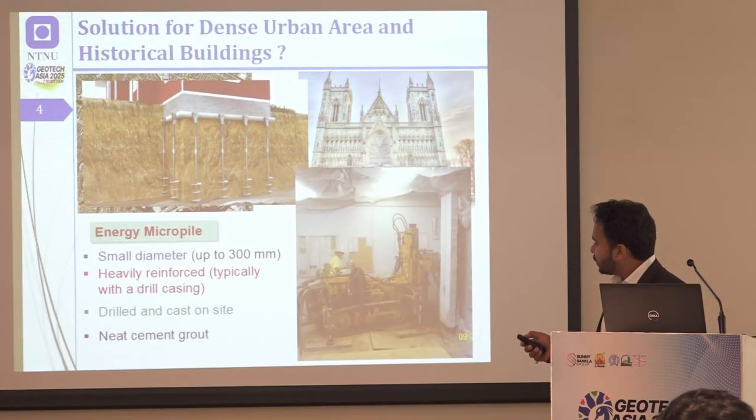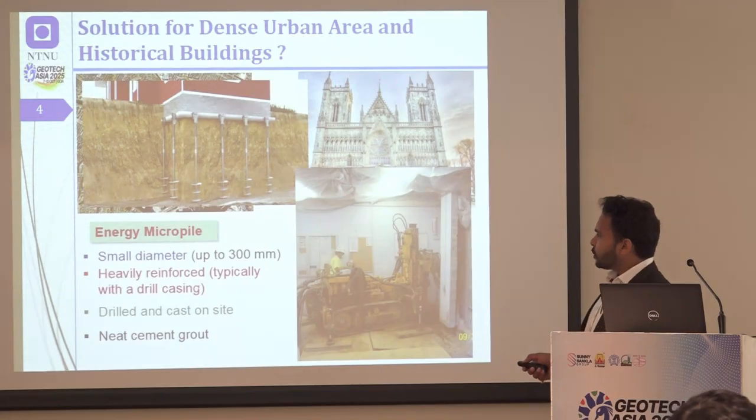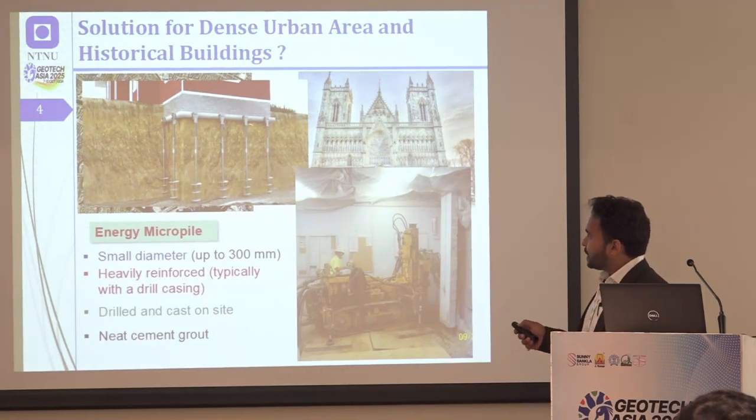What we can do is install micropiles. Micropile is not new; it has been used since the Second World War to underpin buildings and provide additional support to the building in the post-construction period, when we see high deformation.